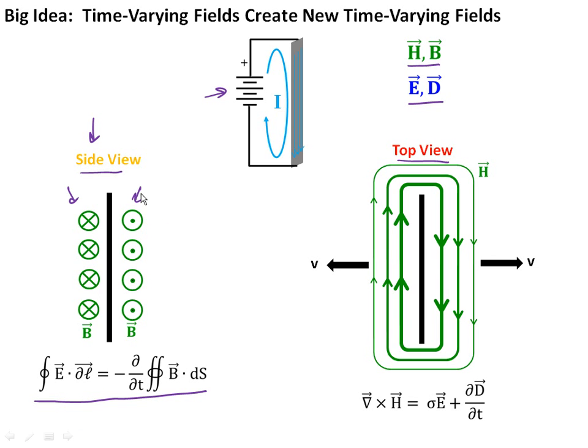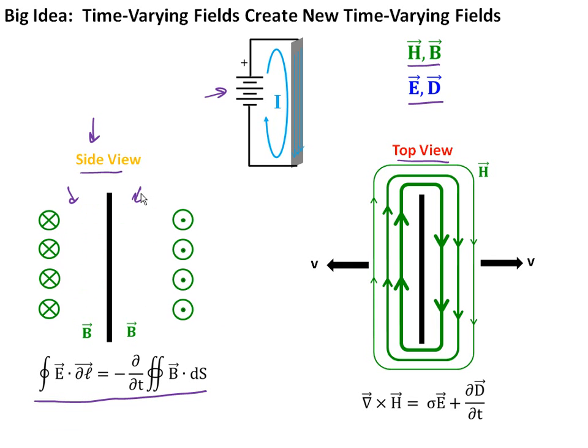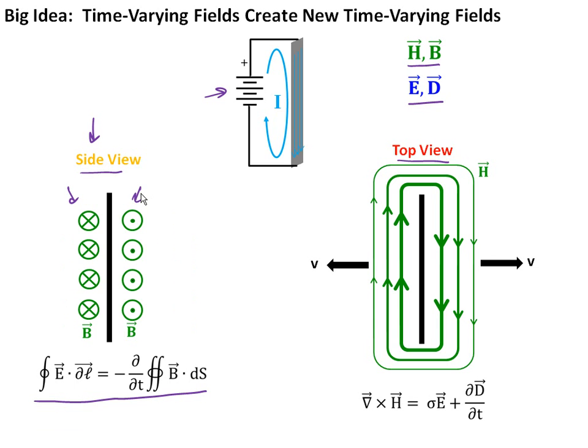And we know that once this is established, at the first moment in time, that magnetic field is going to be really close to the plate that carries current. But essentially what's going to happen is this magnetic field is going to propagate outward. Let's watch that again. There's going to be some velocity, and that magnetic field is going to propagate outward with time. Well, now I can use Maxwell's integral equation. Essentially what I'm going to do is draw a surface, dS, right here in the plane of the screen, and I know that the rate of change of the magnetic flux that goes through this surface right here is equal to the line integral of the electric field that goes around that.